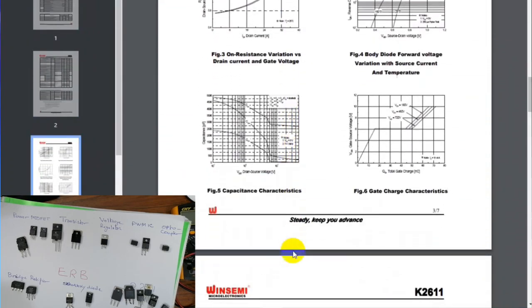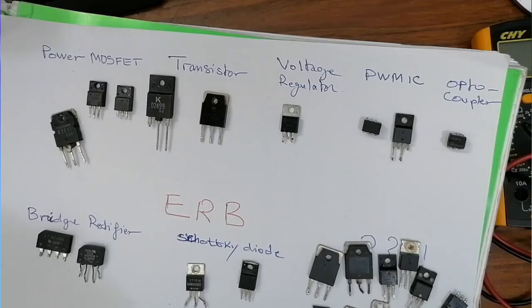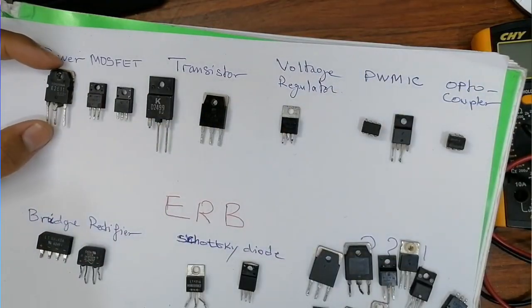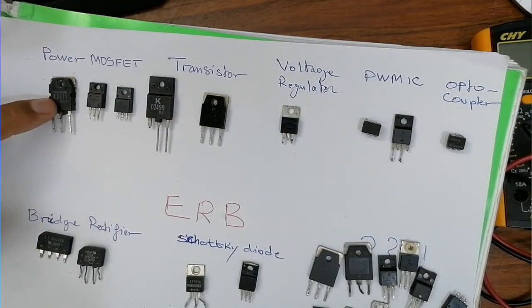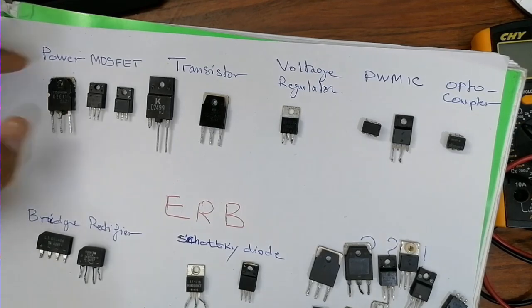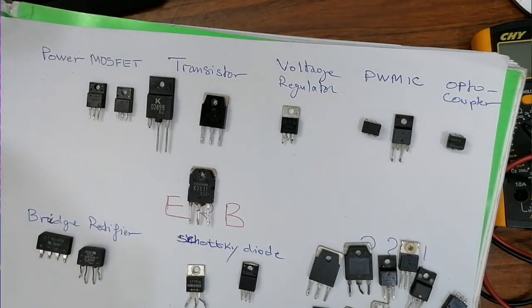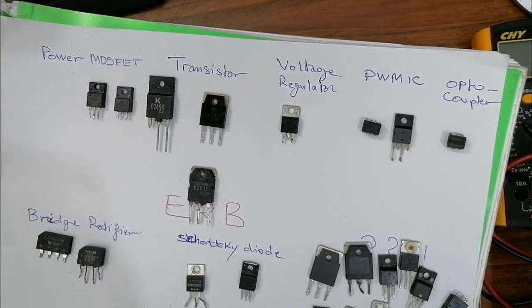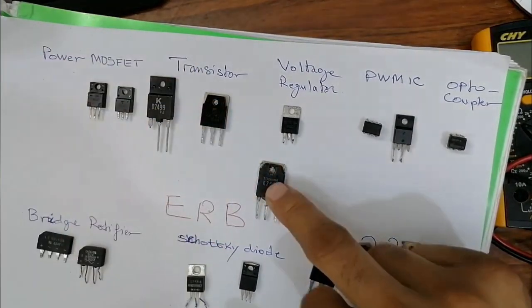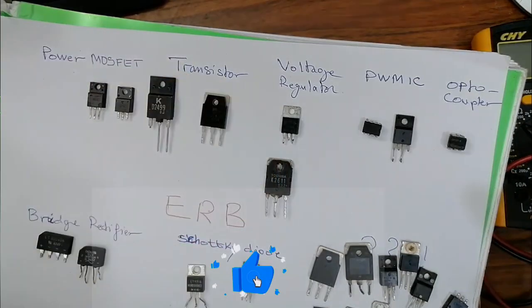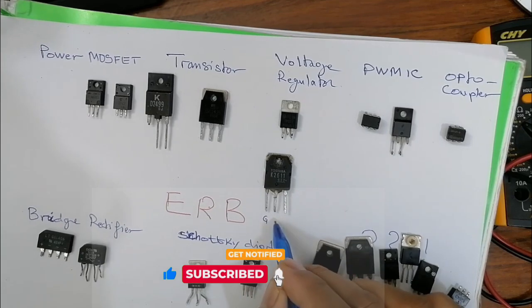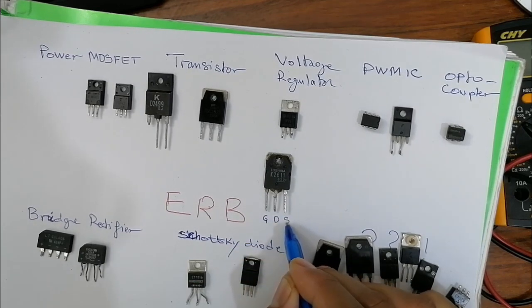So you can use this working principle for all components. Now for this component, this is the MOSFET. Once I identify that this component is the MOSFET, I can test it using the multimeter, with the right method to test a MOSFET. As you can see, this is the gate, here we have the drain, and here we have the source.